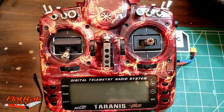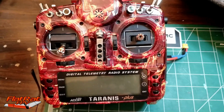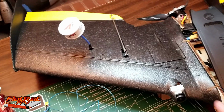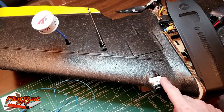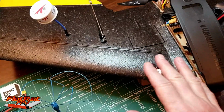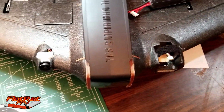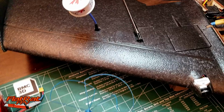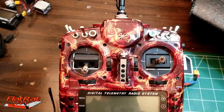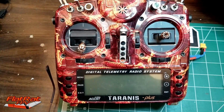Okay, so in order to get the DJI module to work correctly, to get the OSD, you're going to have to change some settings in the Vector. Now, what I'm using is my Cappy right here, and you're going to have to have an analog setup already on here. I had 1.3 on here from before I started using DJI, so that setup is still on here. I normally put my DJI unit right in there, and it works fantastic. So I've got this on 1.3. I've got my goggles all set up like this, and I'm going to show you how to change the settings in your Vector OSD menu in order to get it to work like it's supposed to.